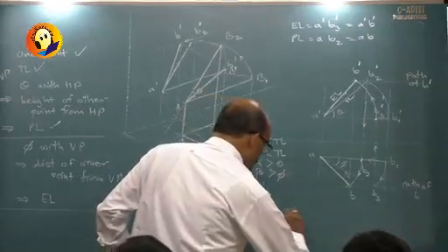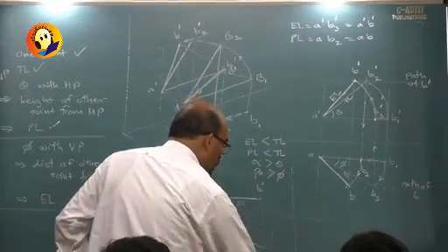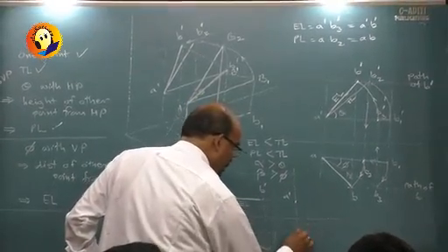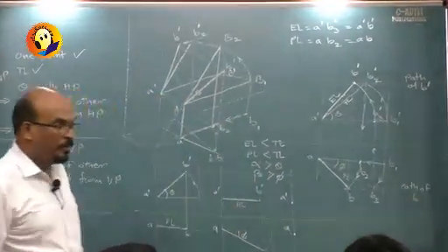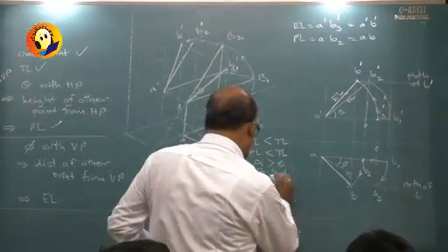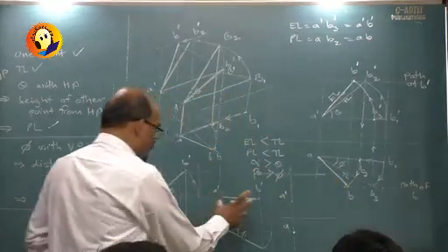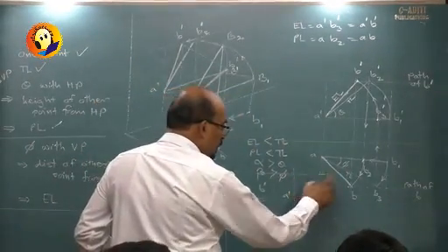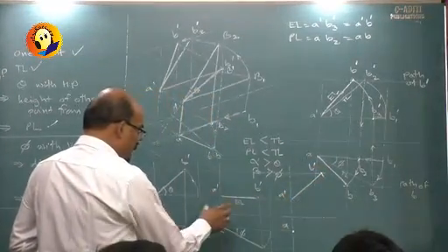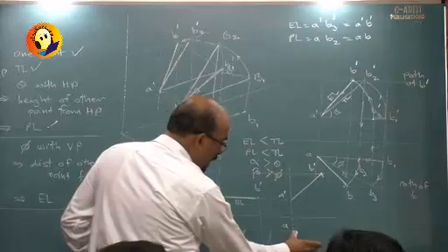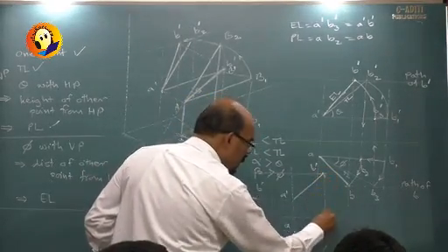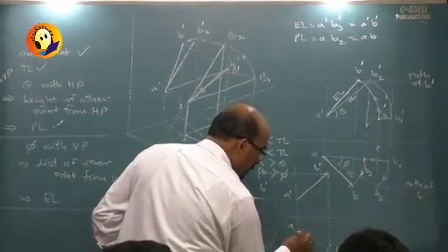So if we are to solve it in 3 steps, this was our first step, this is second step. We again go ahead, we just draw, mark point A dash and point A. Now take this particular elevation length and from A dash cut it on path of B dash. So take this elevation length and cut it here. You will get B dash, join it. Take this plan length and from A cut on path of B. And if you join them, they will be on the same projector.